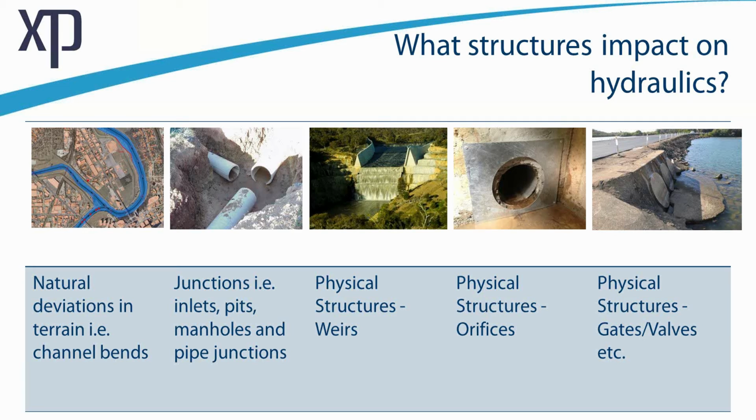In controlled situations, we develop physical structures such as weirs, and we've got a nice slideshow video that we'll present in a moment on the performance of flow through weirs. And this fourth photo is an interesting one, where this is actually intended to be an orifice plate, and this is definitely the odd photo in this set where the orifice plate is actually not restricting flow as it was intended to do. So this is a bit of a failure in construction, and unfortunately these are things that engineers do need to be careful of pursuant to their calculations.